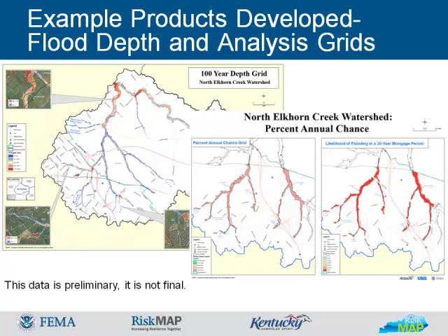It's a powerful communication and planning tool, enabling users to convey that a property may not just be in or out of the 100-year floodplain, but that it may receive a specified level of flooding from an event of lesser magnitude. Using the depth for a 25-year event, simple depth to damage curve calculations can be applied to tell a particular property owner that for a particular event they can expect a specified amount of dollar damages.